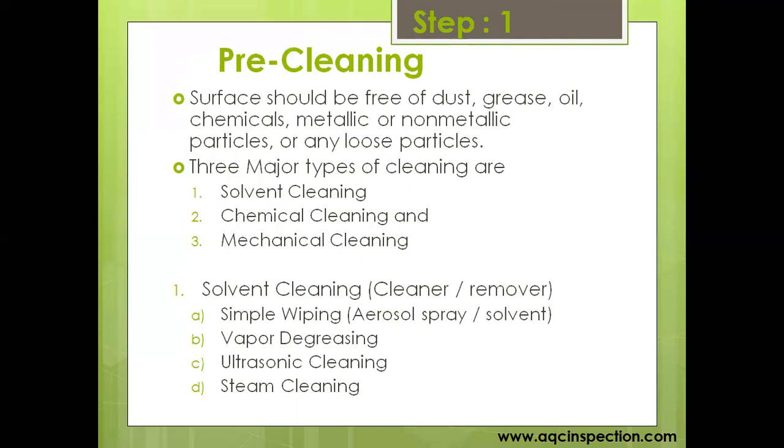Pre-cleaning is one of the critical steps for liquid penetrant testing because any dust, grease, oil, chemical, metallic or non-metallic inclusions can mask the defect. The major types of cleaning are solvent cleaning, chemical cleaning, and mechanical cleaning. Solvent cleaning is further subdivided into simple wiping, vapor degreasing, ultrasonic cleaning, or steam cleaning.